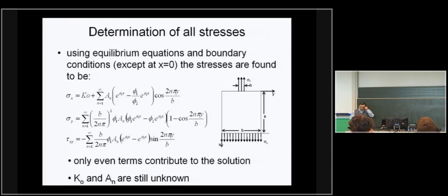And we said this one is a reasonably common situation relating to the stiffener termination problem, where stiffeners in plates adjacent to this one at the top here would be terminating here. So the load from each stiffener would have to find its way into the plate that is shown here. So it would end up being some kind of a very localized load. And that localized load would mean that the stresses would be relatively high in the region next to that point of action of that force. And it would be necessary to come up with the reinforcements.